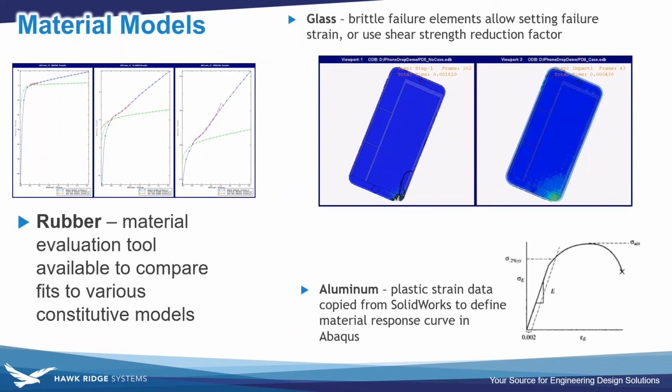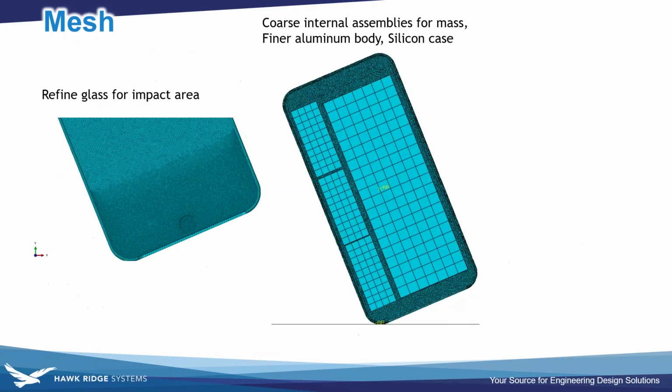And then last, in this analysis, I pulled in a stress strain curve from the SOLIDWORKS simulation tools, and that's part of the workflow that I find pretty handy is that I'll go to the library and pull it out if it's doing a material that's already in that. Since SOLIDWORKS has a full database built in, with Abaqus you can build your own central database of materials, but since I end up working with a lot of different units with the models, I'll tend to just find them from the source as quickly as I can.